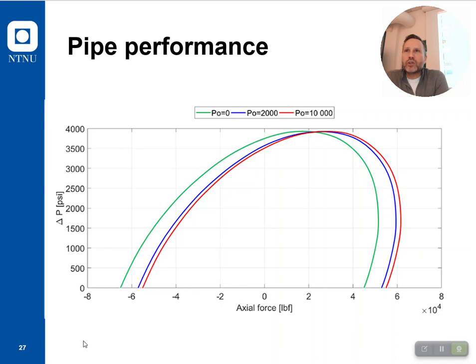That's actually a master thesis here, made by two excellent, brilliant students. They used Lubinsky formula, and that's very simple, really. Theoretically and bluntly, you have the von Mises and you have Lamé, and you put them together and you get triaxial burst.